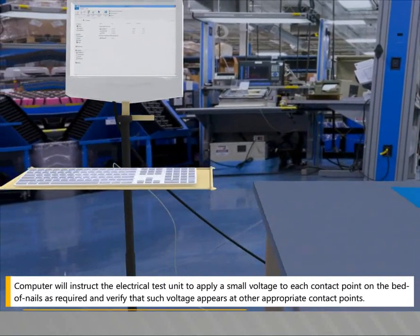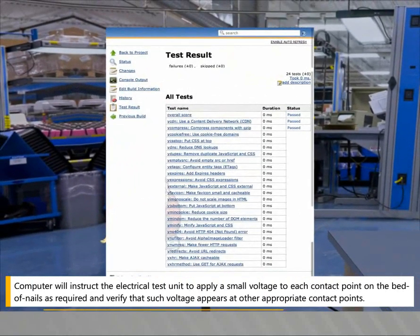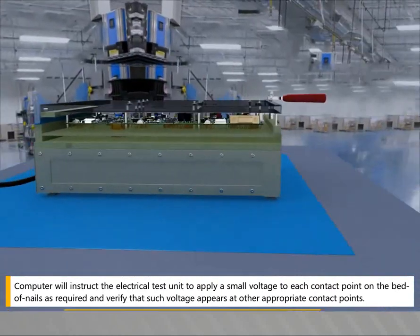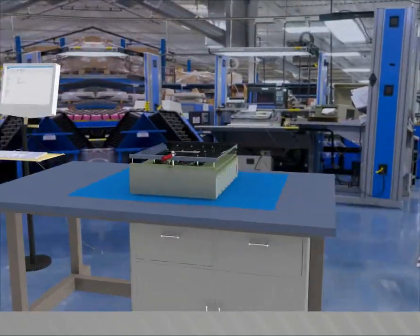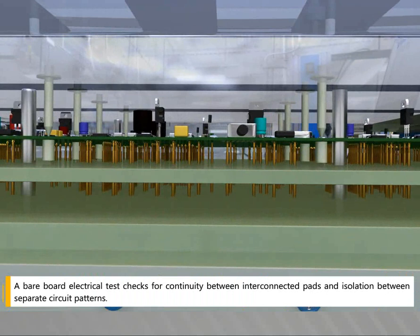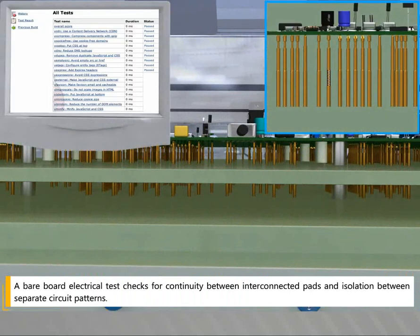The computer will instruct the electrical test unit to apply a small voltage to each contact point on the bed of nails as required and verify that such voltage appears at other appropriate contact points. Test signals are applied and monitored by a programmed sequence from the tester's dedicated processor or computer.